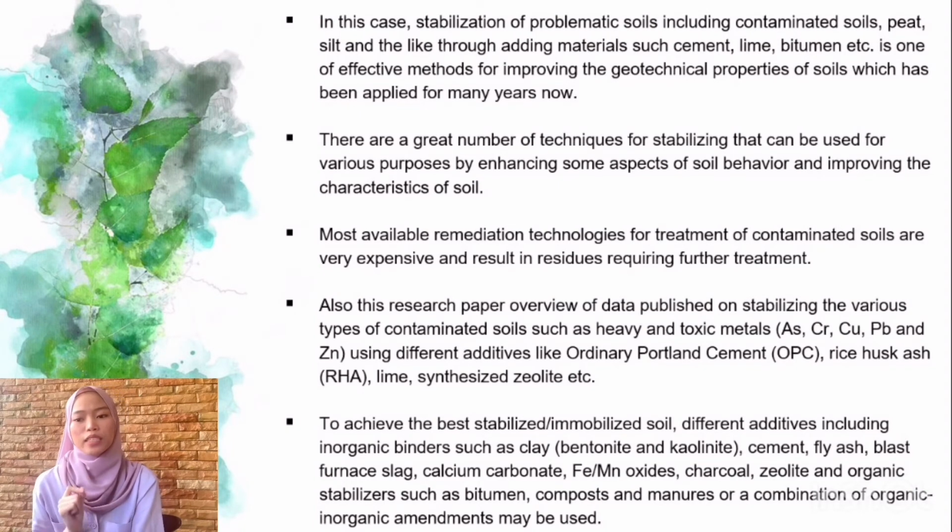To achieve the best stabilized or immobilized soil, different additives including inorganic binders such as clays like bentonite and kaolinite, cement, fly ash, blast furnace sludge, calcium carbonate, iron or manganese oxide, charcoal, zeolite, and organic stabilizers such as bitumen, compost, and minerals, or a combination of organic and inorganic amendments may be used.